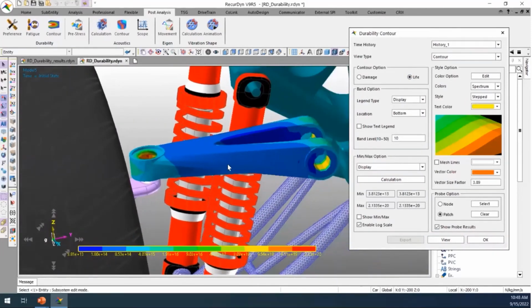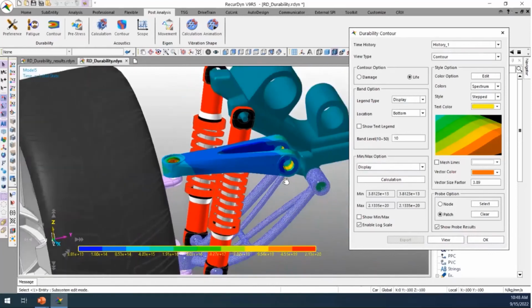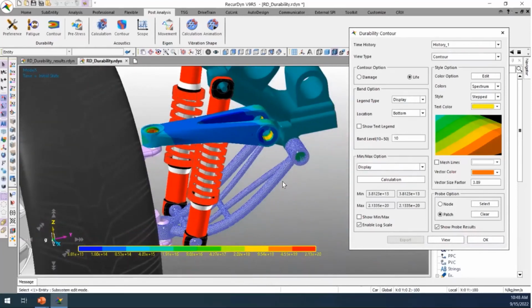So we now see our lifetime is basically an inverse of the damage plot, which makes sense. We see that our minimum value has a very large exponent. So this part is probably fine. You actually go through the tutorial later on. In the tutorial, the point is to show you, okay, this part is good, and this part is not okay, and needs some work to not be a huge problem with warranty claims later on.